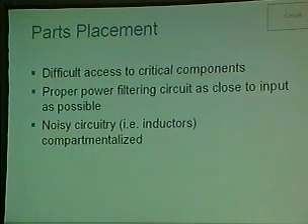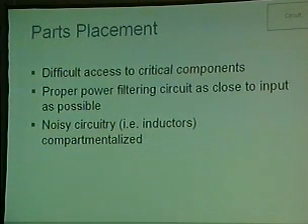And the reason these attacks were so easy is because these parts were easily accessible on the PC board. So as I opened up the product, I could easily clamp on to the EEPROM devices. I didn't have to deal with any kind of tampering or obfuscated placement of the parts.